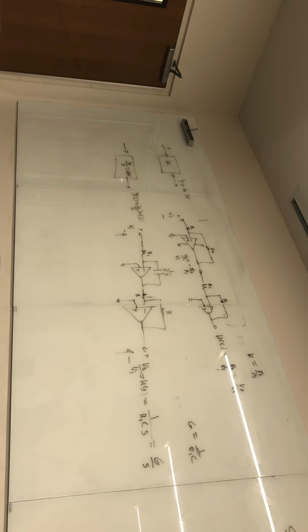I'll show you an example of this so you really appreciate it. A typical low-pass filter is this one, and you see it all the time. If I have a resistor R and a capacitor C, and this is my output voltage and this is my input voltage, then the ratio of V out to V in would be equal to H of S. Do you agree with that, class?